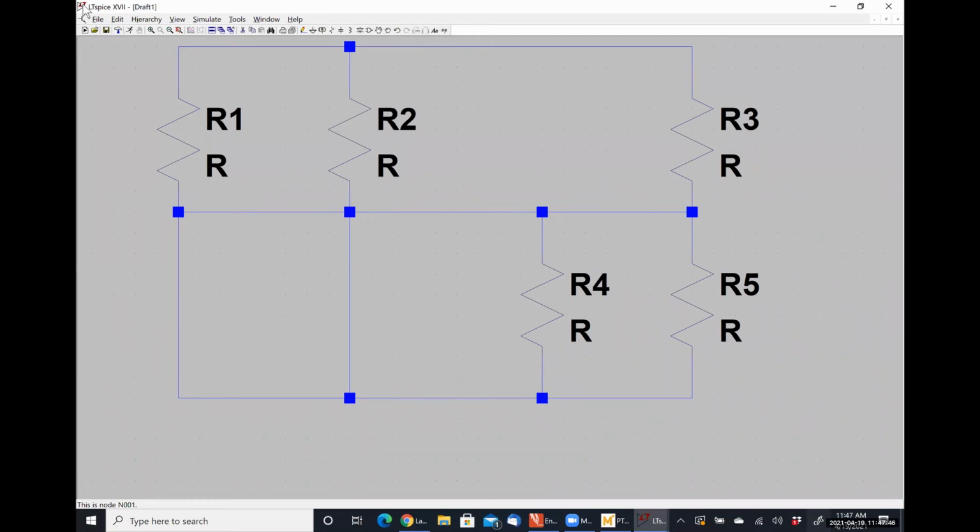So my phase angle measured in radians divided by my frequency measured in radians per second gives me units of seconds, and then I would multiply this guy by 180 degrees per pi radian, which would convert my angle from radians to degrees.